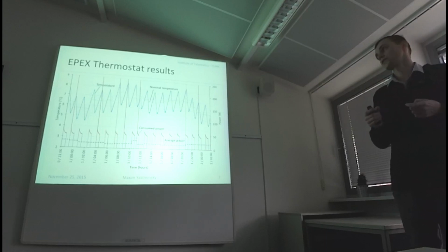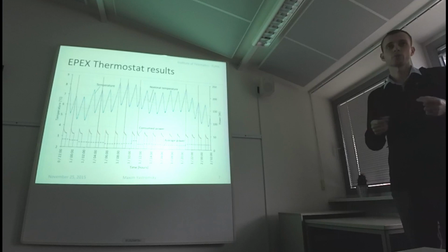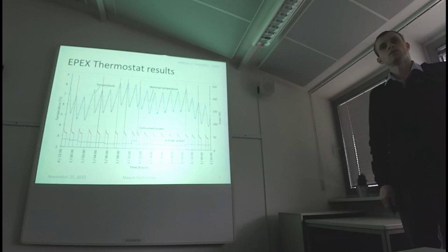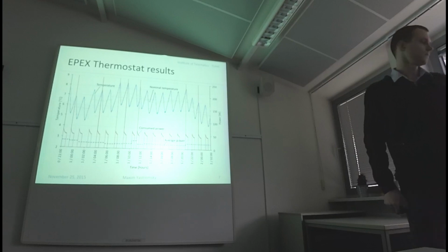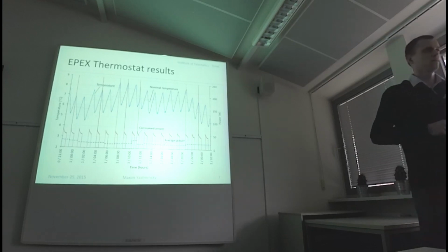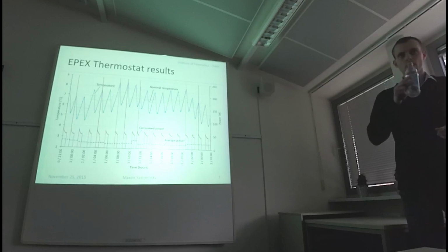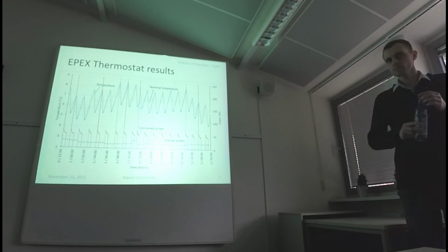It lasts only about 3 seconds, but every start there is a very big peak. Or is this a measurement error? Could be, but I guess they have a capacitor in it to compensate reactive power. If you switch it on, it charges, and that creates a peak. I guess it's something like that.